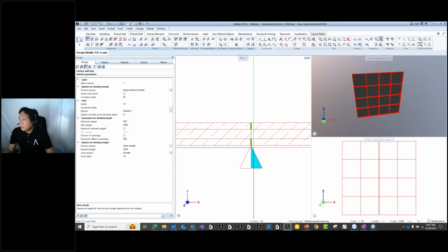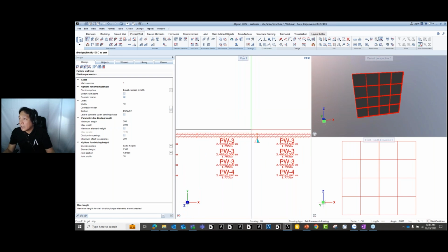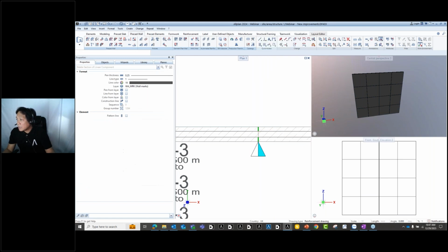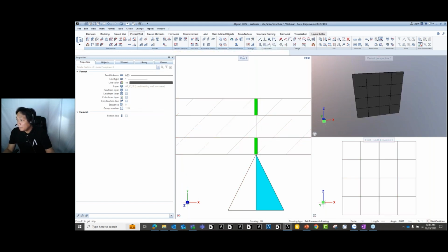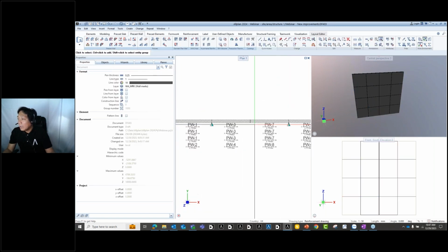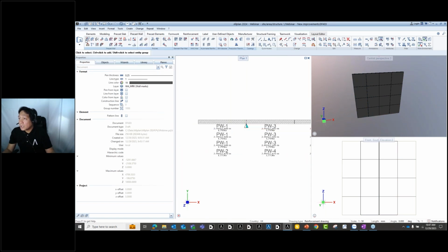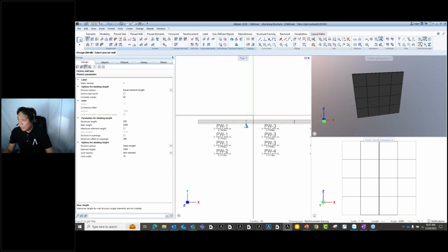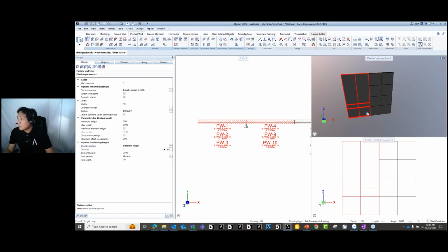And let's say, for example, this part will be totally different. So what I can do here is right click. Let's say the division is not like this, but this part will be different. So I can remove the section. So they're totally separated, different walls. Then from this part, I can do division. Select this part, and let's say not the same height but different heights. As you can see, it's now different.